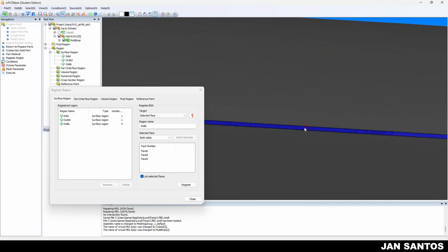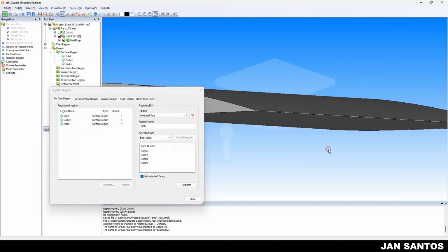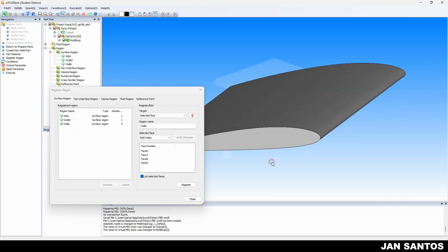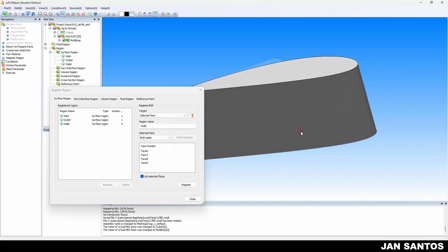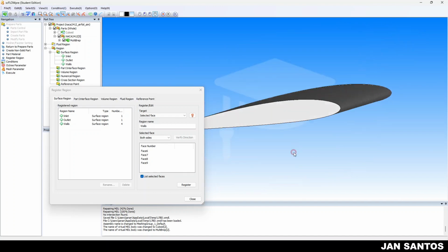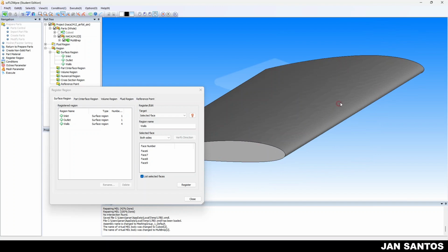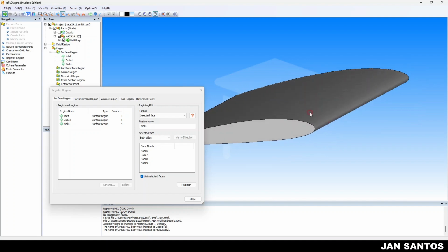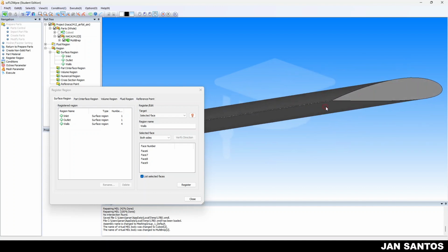But if you zoom in, let me go ahead and zoom in, there's still a part of our airfoil that is still highlighted as blue. Click on that, okay? This might not be the same case as your airfoil. Maybe you did it in another way, or you have more inconsistencies here, or more relations to your airfoil to create this curve. Unlike mine, it is smooth from top to bottom. You might have a line here to create this curve, another line here to create this curve. You're going to need to click all those.